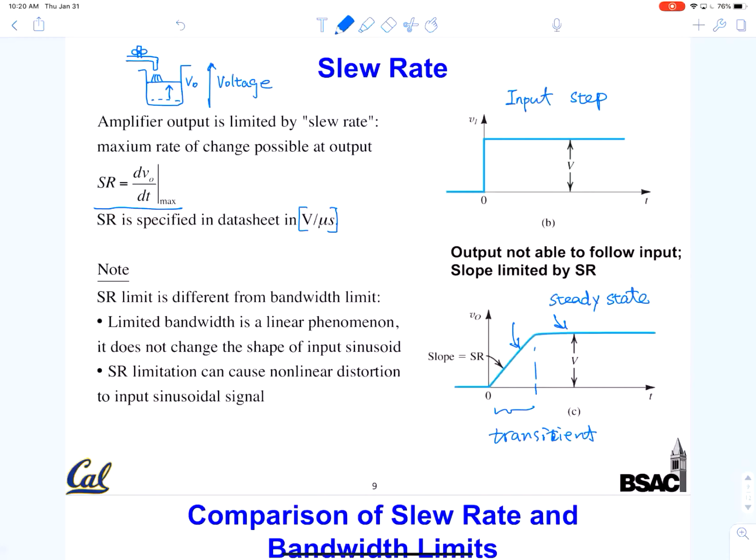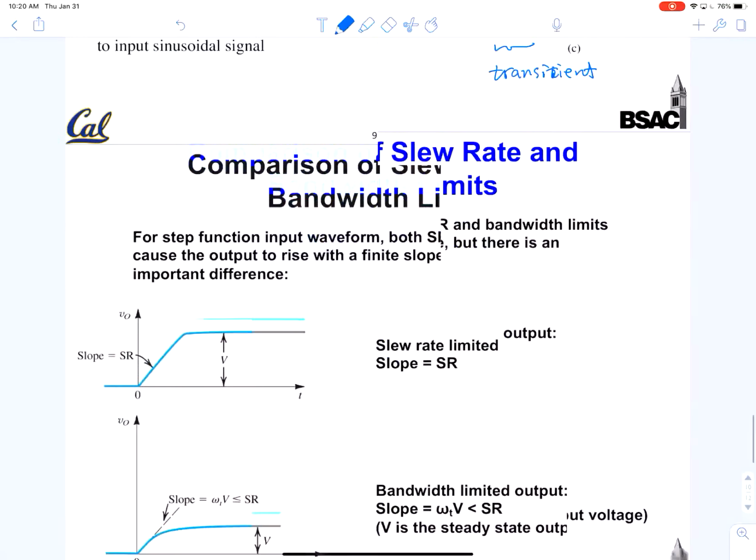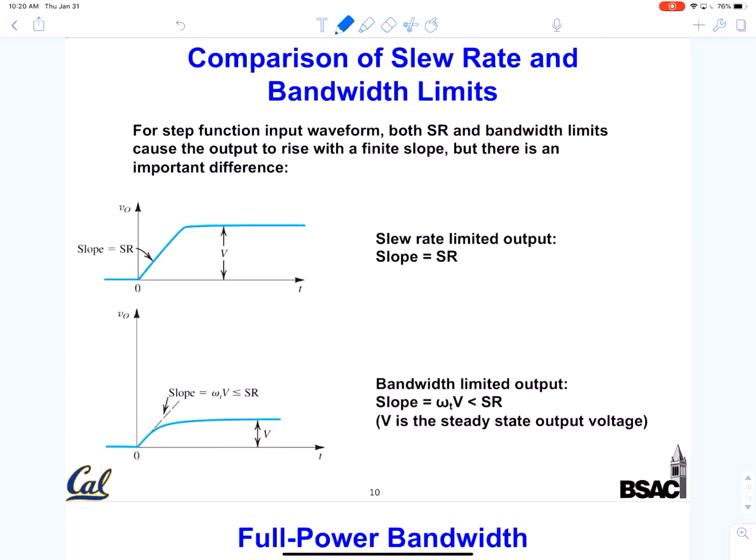If you have an application that exceeds any of these available op-amps, you need to design your own op-amp. Then you apply even more tricks to make that higher. Usually, high slew rate comes at a cost. Circuit design is like engineering: there's no free lunch. When you get high slew rate, you usually suffer some setback in other specs, and you have to decide whether that's livable for you or not.